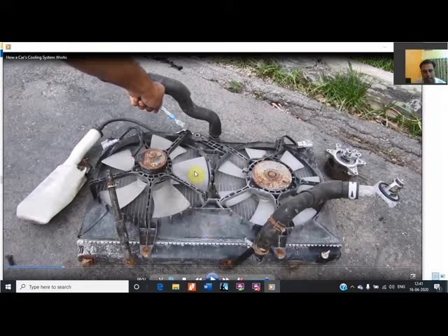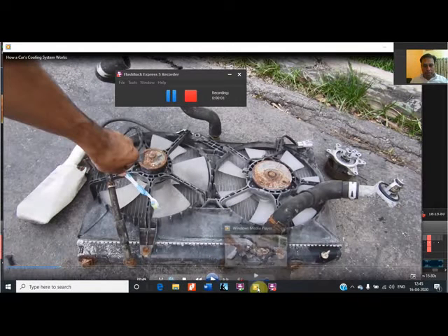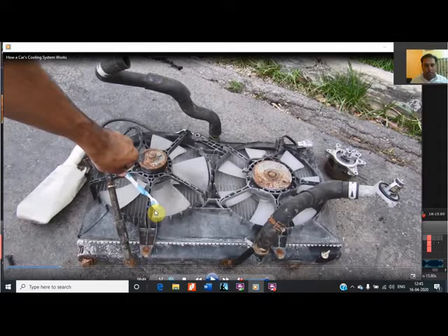One by one he is showing that the coolant used to enter from the upper side, and it used to come out from the lower two sides. This is being shown over here. In the radiator, on the lower part, two hoses are there, because when we want quick cooling of the coolant, from one hose the automatic transmission is there, because they have removed the radiator system of the automatic transmission. So that's why two hoses are there at the bottom for taking the coolant. And at the upper side, one hose is there because hot coolant used to enter from this side.